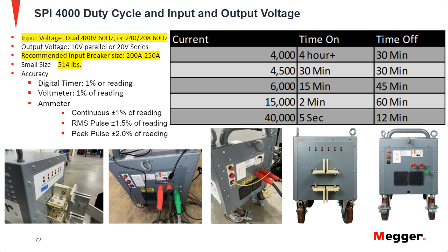With that being said, it's always a recommendation for molded case breakers to be millivolt drop tested. That's typically a common rule of thumb. Now, your DLRO can still test your contacts, and can still test air frame breakers fine. In regards to what current you should be using, you can use 10 amps for, I think, breakers rated under 500 amps, or 100 amps for breakers 500 amps or more. I might need to double check that as far as standard, but I believe that's right. Dozy, if you want to chime in on that.